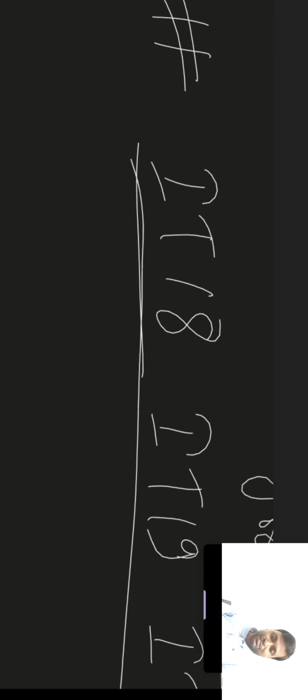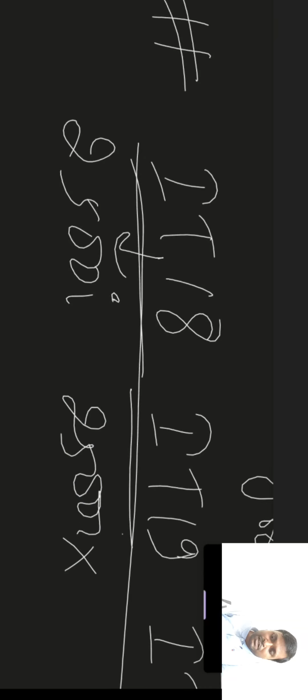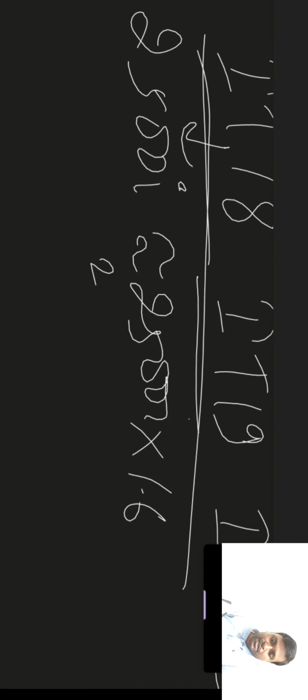and all these tolerances will be in the R5 preferred series. So if the value of IT18 is exactly 2500i, then the value of IT19 will be 2500i into the R5 series, that is multiplied by approximately 1.6, and that will be 4000i.